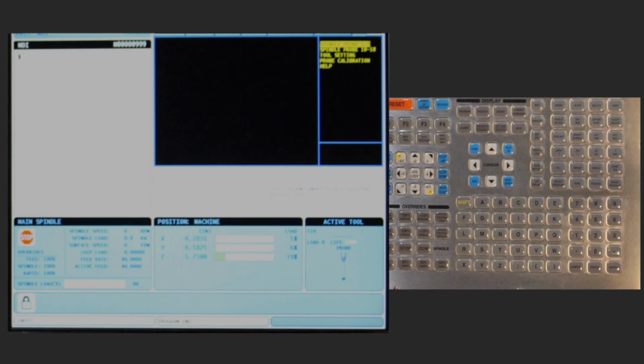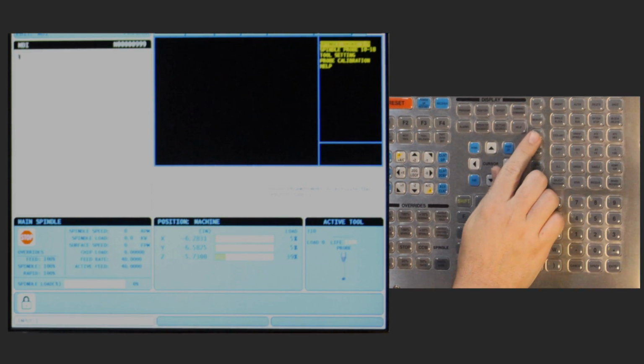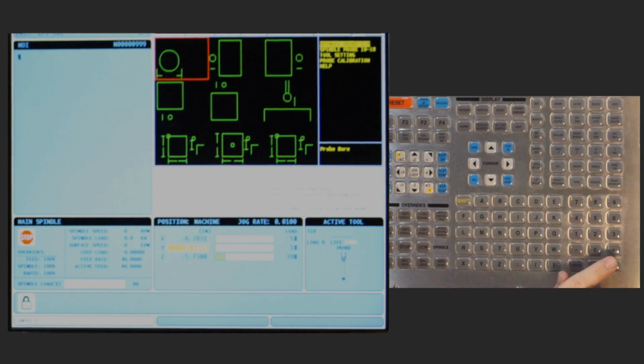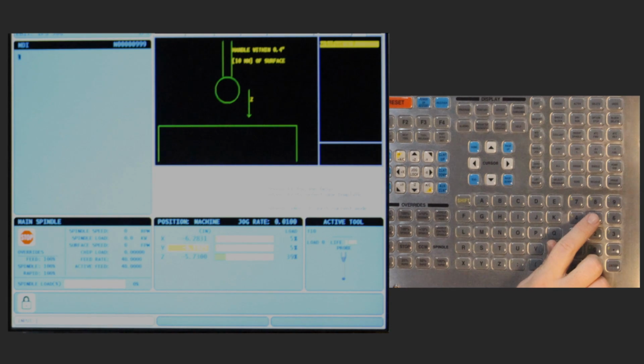The center of the cylinder is now set as the work coordinate origin. Note, the Probe Boss routine does not probe the Z-surface. We need to probe the Z-surface separately. Be sure to use the same work offset number used previously, in our case, 54.